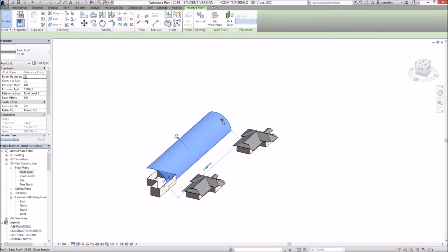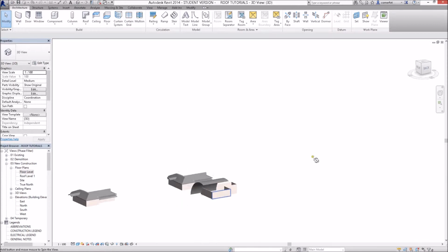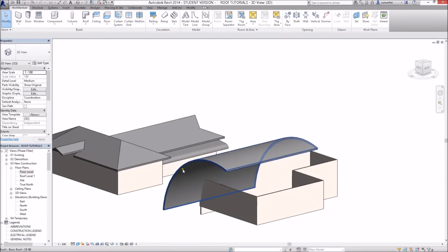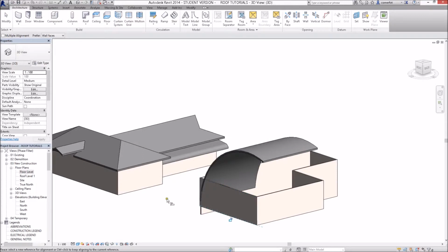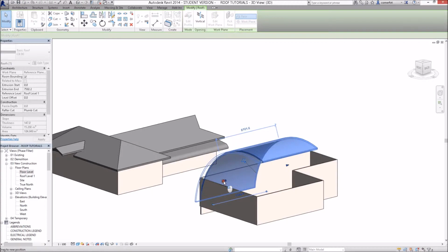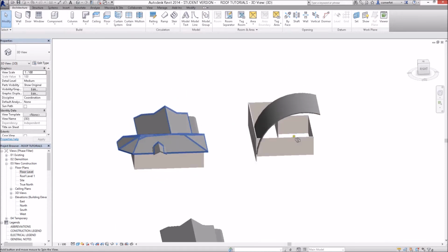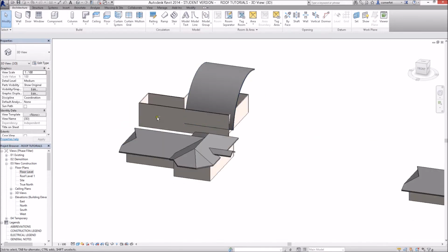Okay, yes, this again. So we can just stretch these back to where we wanted it to be, or you could have defined that at the roof start and the roof finish. So we probably want something like, I'll use the align tool again. AL for align is my shortcut key. Click on that surface, click on that surface. They're now aligned, and you probably want some sort of an overhang, so I can use the grip just to extend the overhang out by a prescribed dimension that you wanted to go to. So I've got that roof happening there at the moment now.